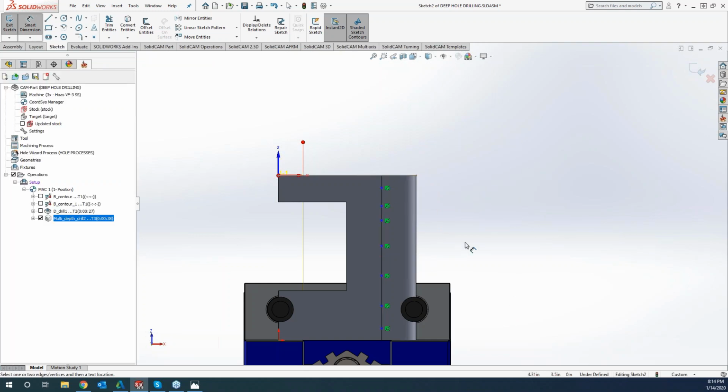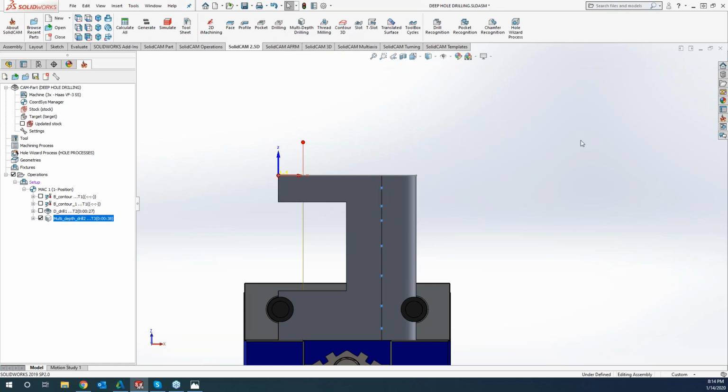Let's say for the long drill bit, the vendor has specified for maybe the first inch, I want you to do this RPM and this feed rate. For the next inch going down, I want you to use this feed rate and this spindle RPM. So we've got that set up. We'll just label these as our step downs that were specified by the manufacturer.